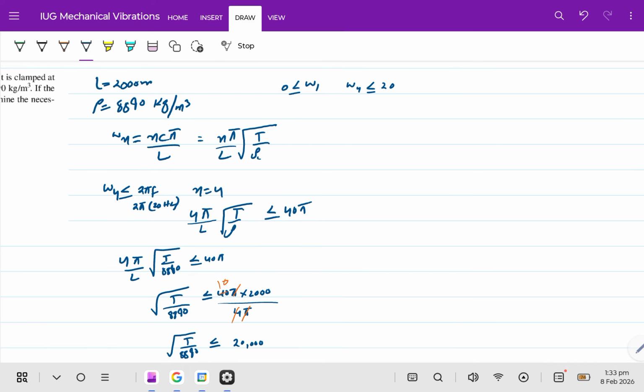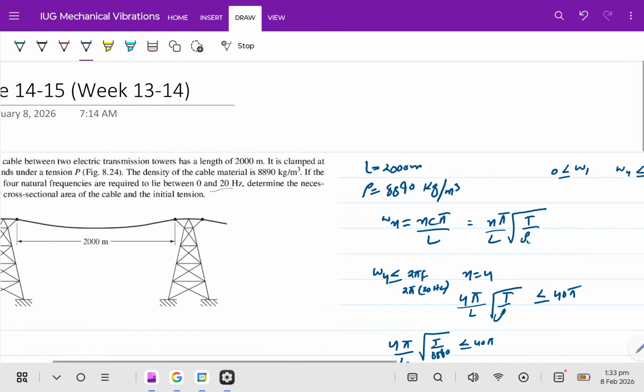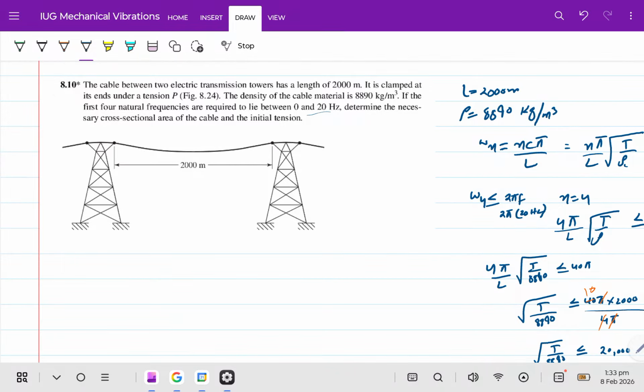So that's all for this lecture. I will share some similar problems for the vibration in beams or bars, and I will try to upload some practice problems or a short video discussing the various problems in vibration of beams and bars. You should have a look at it, and you don't have to worry about the whole calculation. Just try to understand the kind of problem you have, try to understand the boundary conditions you have, and directly pick up those boundary conditions and the concerned equations from the solution that we have done before. Or if you don't have the solution directly, just use the governing equation, input the boundary conditions, find out the frequency equation and the constants a, b, c, d, and you will have your solution.